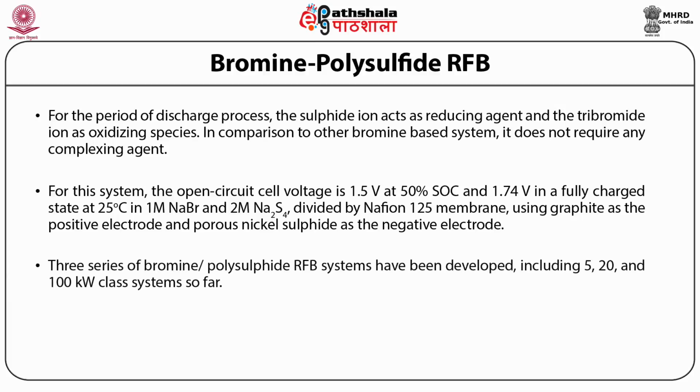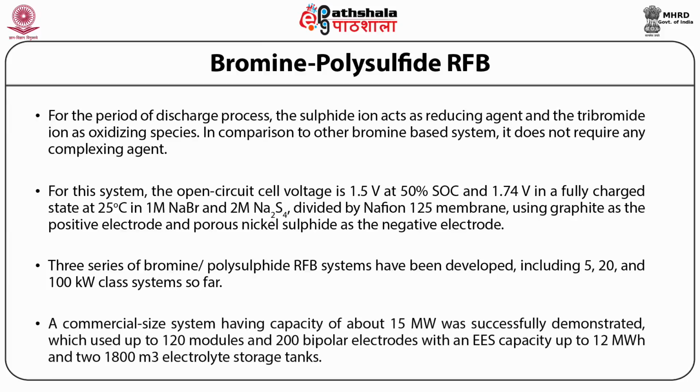Three series of bromine polysulfide RFB systems have been developed, including 5, 20, and 100 kilowatt class systems so far. A commercial size system having capacity of about 15 megawatt was successfully demonstrated, which used up to 120 modules and 200 bipolar electrodes with an EES capacity up to 120 megawatt hour and two 1800 meter cube electrolyte storage tanks.